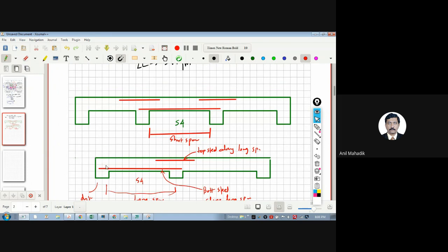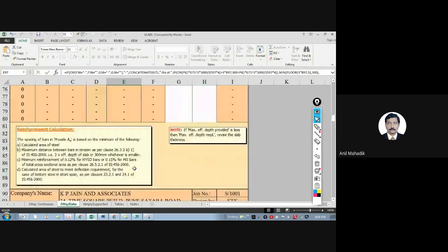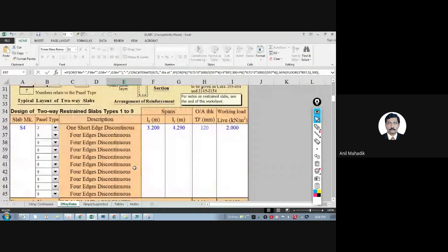And there is ideally no requirement of steel because there is no negative moment. Okay. But as I told you yesterday, for durability purpose, generally we provide minimum steel. So you can provide minimum steel here. No problem. Okay. So this is the detailing of a two-way slab. And you can design this like this. So you can assume any boundary conditions and put the steel accordingly.